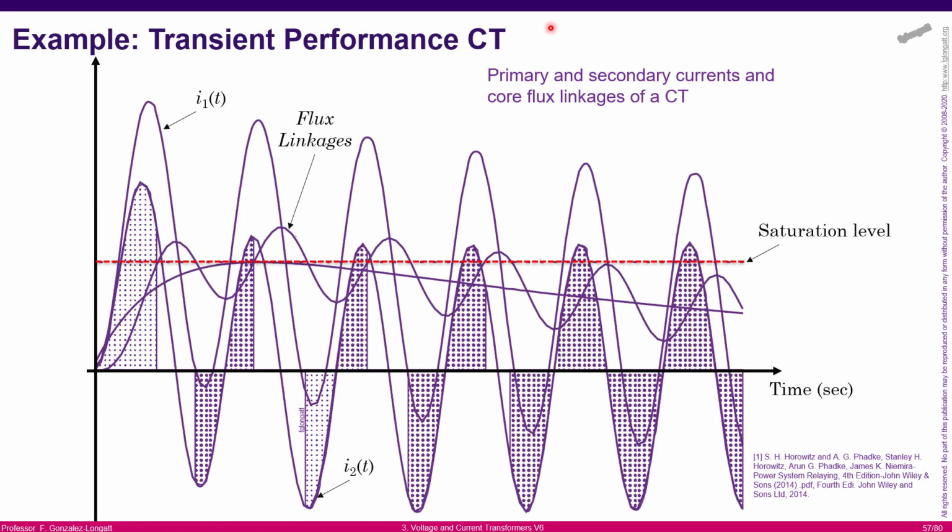In that case, as you can see, the saturation level is reached several times when the flux linkage is changing over time. Okay, what we want to say is, in time domain representation, the analysis is far more complicated, especially if we include the inductance component of the burden.